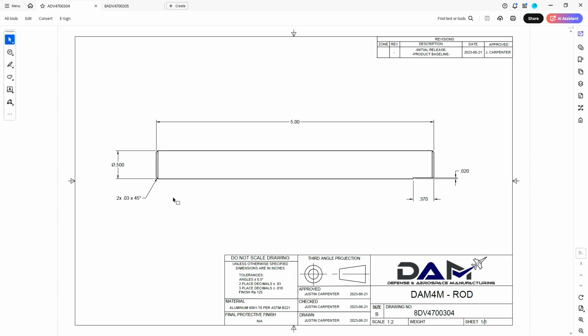So on lathes, it follows the profile, and typically on mill parts, I'll put features like this chamfer on as a separate feature at the very end so I can suppress them. On a lathe, it's helpful to have that profile in case you need to select on it to drive tool path on it. But you don't always know your approach depending on what you're making. So we're using Fusion 360. We're going to model this part, and let's get right to it.